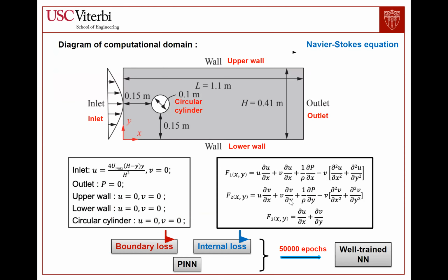After using the heat equation to prove our PINNs are working well, we started to work on computational fluid dynamics. The first work we need to do is to define our boundary conditions. As we can see in the picture, we've defined our upper wall and lower wall to have a velocity of 0, and the left boundary is considered to be the inlet boundary, with a parabolic horizontal speed, which will get to 0 at the corner. It can guarantee the continuity of our boundary condition.